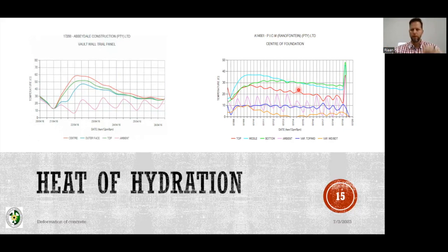They will prepare section A or section 1A, and then 2 days later, section 1B, section 1C. Instead of just completely preparing section 1, they were able to stagger. And then as soon as C is done, 2 days after C, or D, they were able to move into section 2A, move shutters over there, because our temperature gradients completely removed the risk of heat of hydration cracking.